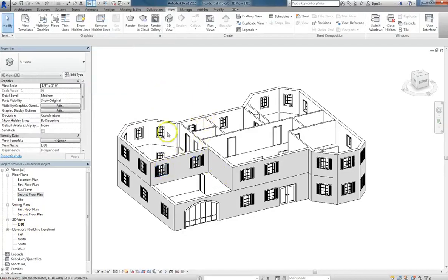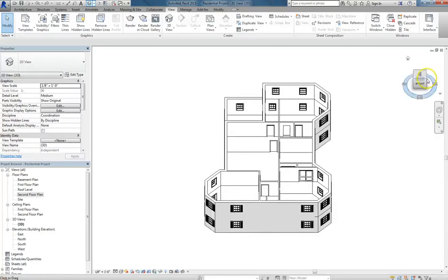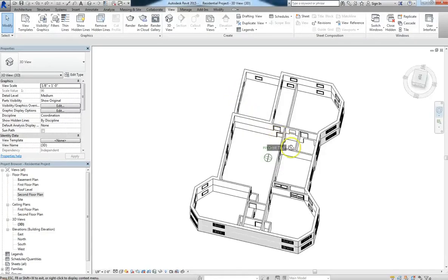As we navigate around our object, remember, you can always use the cube there in the upper right-hand corner, but a lot of times I like to use the wheel. Now, you can select a variety of different sizes for the wheel. There's the mini, which is honestly one of my least favorites. Or you can choose the full-size wheel. This is what I normally use. You can orbit, zoom, center, orbit, and generally just move around your model in a bunch of different ways.